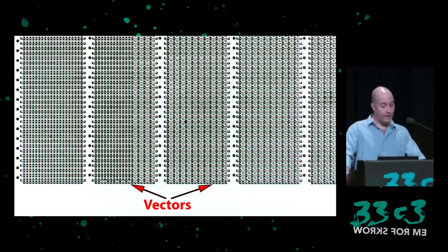After extracting the bits and decoding them into bytes, the hex dump can be studied. There's a copyright 1997 CHCC ASCII string in ROM, which is helpful to identify when the ROM has been decoded correctly. If you can read the ASCII text, then surely the bits are in the correct order. The decoding in this case is just a matter of organizing the bits into bytes. It's quite straightforward. There was no scrambling or anything else that was complex.